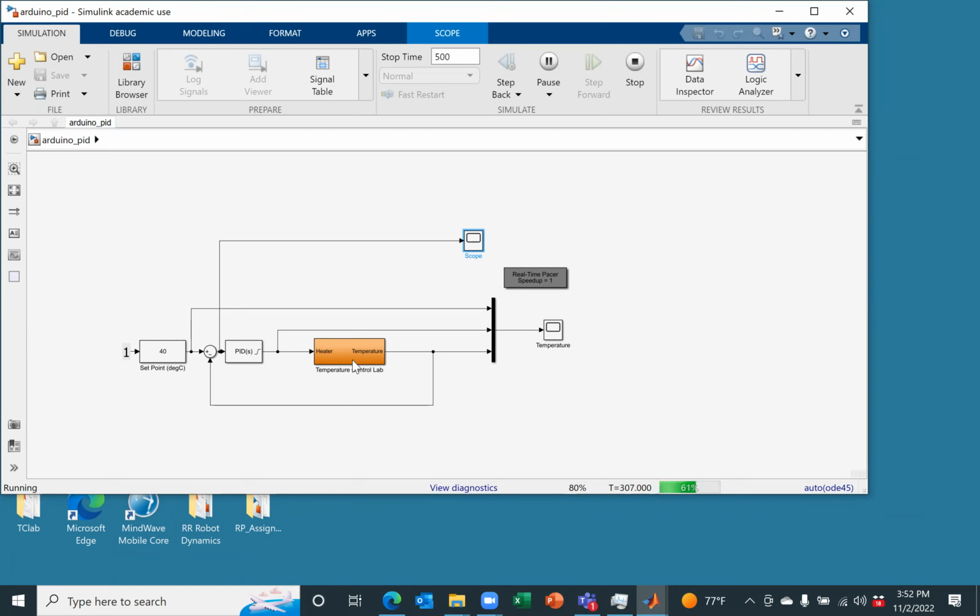Okay. So there are actually guidelines and rule of thumb. The way you typically design a PID, first and foremost, you design a proportional gain. With a proportional gain, as you can see, we will get quick response. But the problem with proportional gain is we are going to get an overshoot. Okay. And then no matter how much proportional gain you add, you cannot eliminate the steady state error. Do you agree with me?